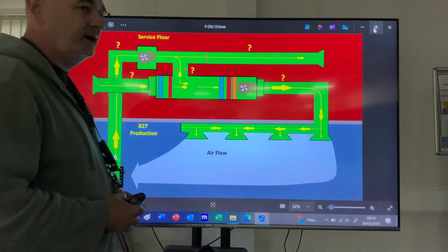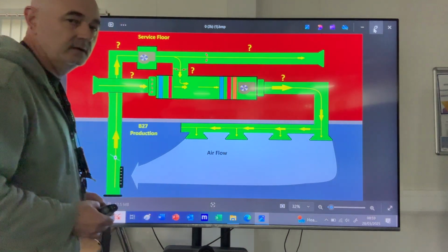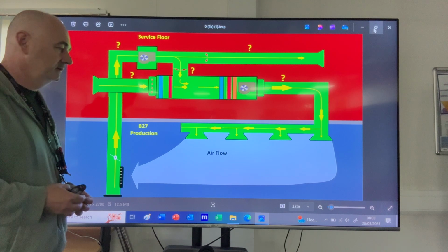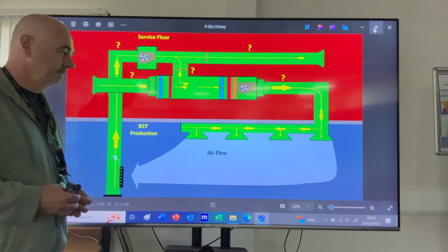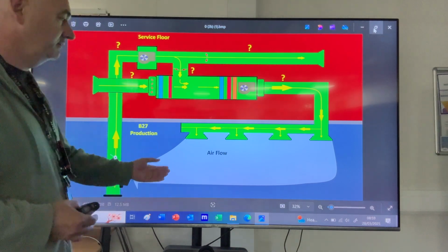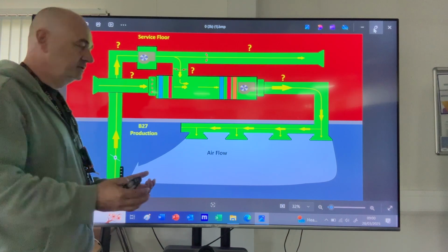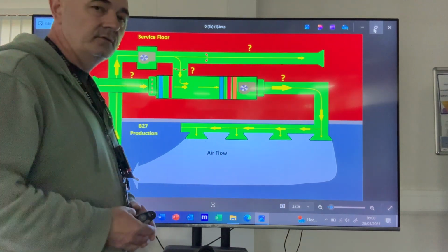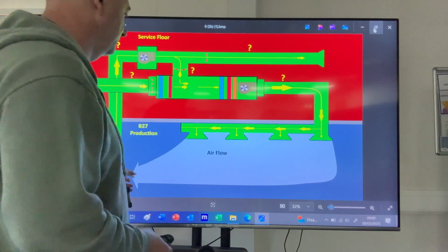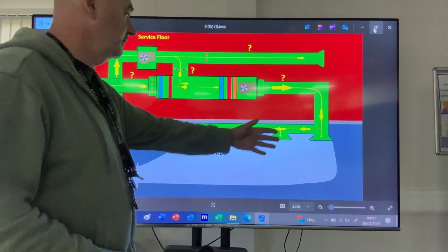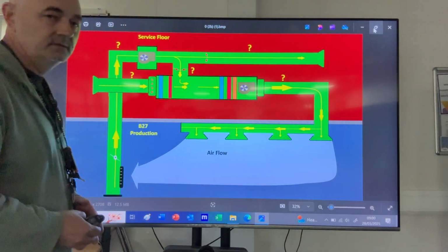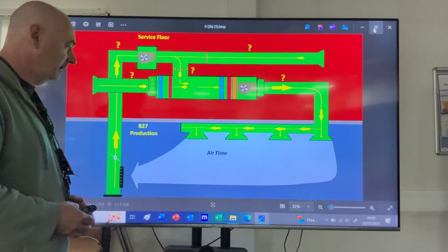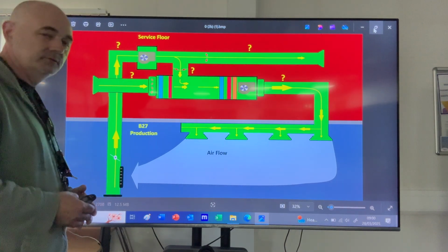Other issues in the past, I was dealing with problems in 2019 when I've been employed. People have the bad habit to go into the room and manipulate the dampers which are fitted in the bulkheads, disturbing the air distribution through the room. Like you'll see here, the air takes only one direction because the rest of the extractor dampers are either blocked or closed.